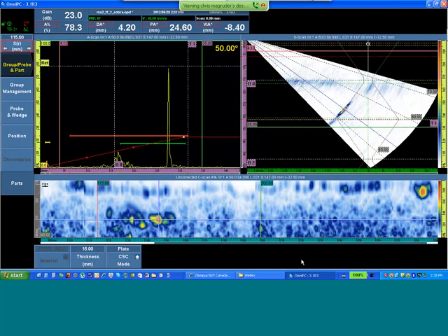And as you see, we see almost the same user interface as the instrument, but spread out a little bit longer. Looking at this weld, this was from a Cobra one-sided inspection on a component that was 16 millimeters thick. So I see my skip lines here at B0 representing 16 millimeters in true depth and 32 millimeters representing the full skip.